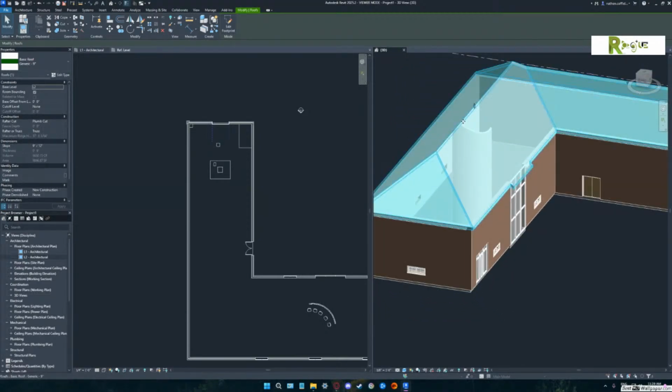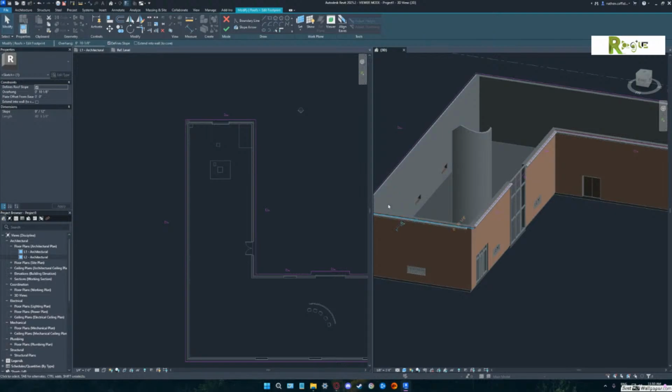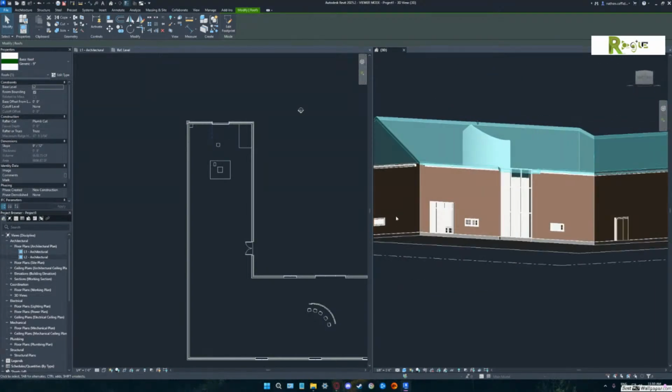You know the difference between a gabled roof and a hip roof? No. Okay. What you have right now is all hip roofs. If you click on the purple line closest to us in the 3D view, down at the bottom, right there, click on that. Now you see where the slope is, and it says define slope up there. We don't want that to have a slope, so check that off. Okay. And then hit your green check. Now you see what that did? Now you've got a flat end of your roof.